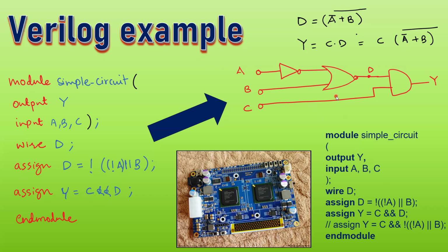So you see, this is how you have successfully written a Verilog module code for a simple combinational circuit like this. And in this module you understood how to use the different keywords such as module, output, input, wire, assign, and end module. You understood how to define input and output ports. You understood how to write the expression for the wire, and most important, the boolean operation that you wish to perform, and then accordingly implement the hardware, which is the combinational circuit using logic gates.